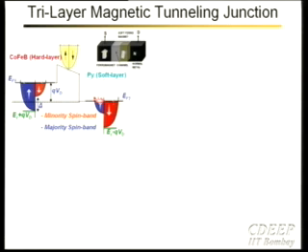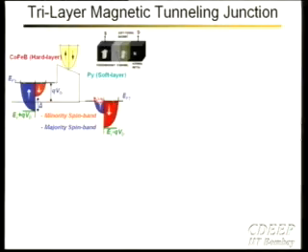But one of the things that we've been looking at, and so are a whole bunch of other folks, is the magnetic tunnel junction. It has a ferromagnet on one side and another ferromagnet on the other, and in between you have a very thin oxide, or it could be a metal, depending on whether you call it a spin valve or a magnetic tunnel junction, which uses the oxide. One of the ferromagnets is going to be a hard magnet, meaning it has a fixed up or down spin, and the other is going to be a soft one which can be changed. If I look at such a structure, shown on top, there are two ferromagnets on the two sides, and the right side is the normal metal for connection. It shows two spins in the same direction, the up direction, and sandwiched in between is the channel, which is some sort of an oxide. So it's basically a tunnel junction that I'm looking at.